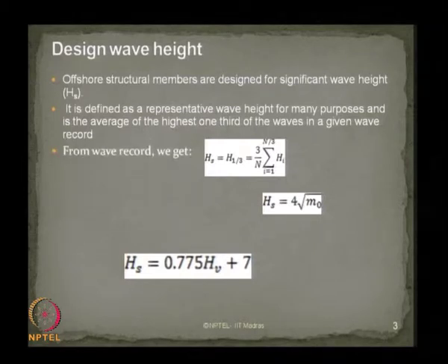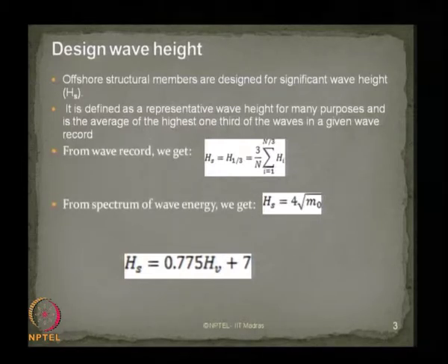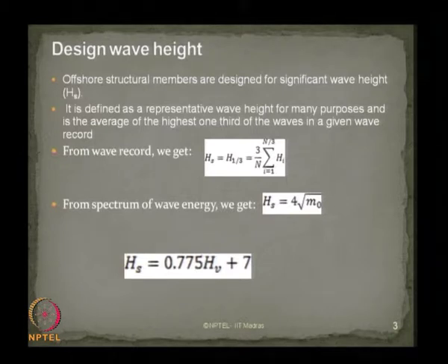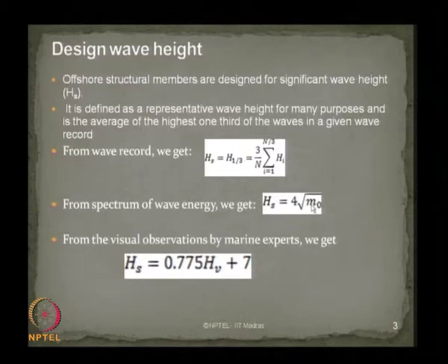In the absence of this, if you have the wave spectrum, or the spectrum of the wave energy, we can also find the significant wave height from the spectrum of wave energy using this equation, where M0 is the zeroth order moment of the spectrum.